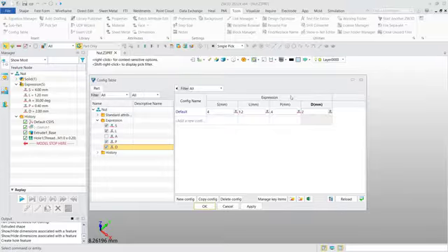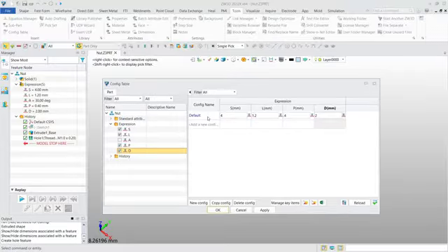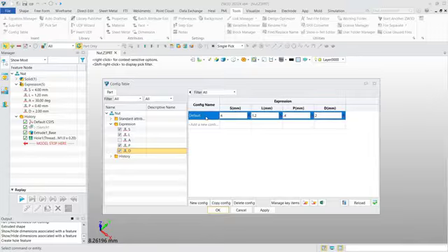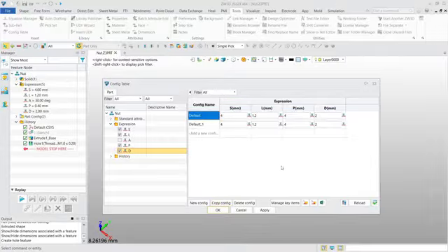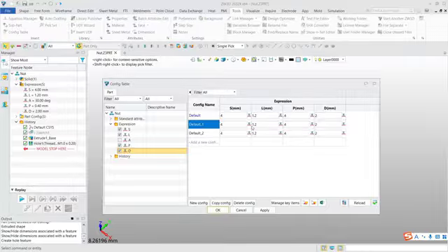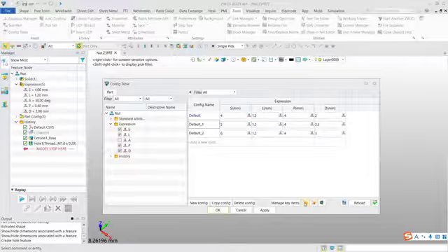We add this 4, and then we can create more part configs in the config table. There are two ways. First way is we can just copy more and we change the parameters. For example, 5, 6, 5.2, and 3. This is the first method. And another method is we can use Excel to help us more quickly. For example, you can export the current data and add more data in Excel, then import again.